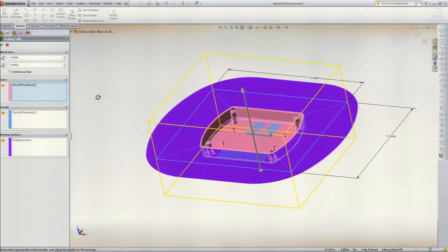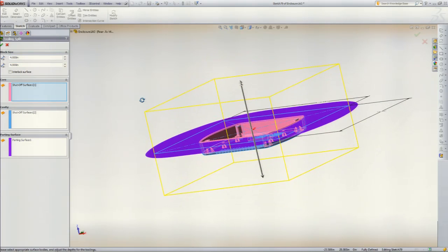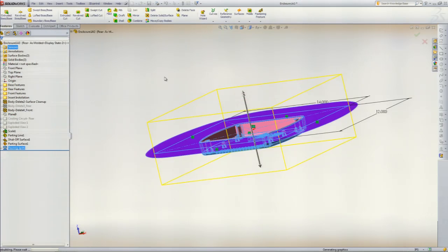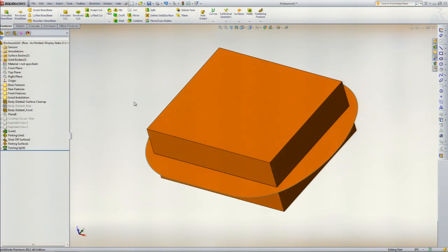And here. Okay, I already filled out these fields practicing earlier. They're still here. But I have tool steel 4 inches on each side of the core cavity split plane. You can change this to 3. I'll just do that for now. And now you have your mold base or mold inserts, depending on what direction you're going on the tool.